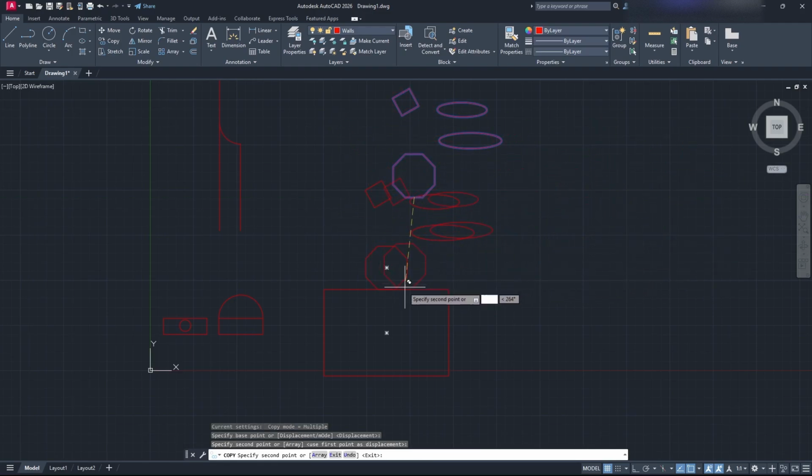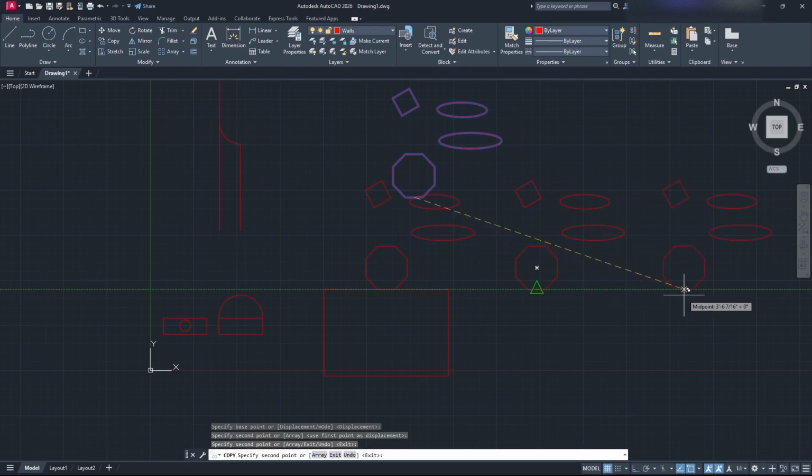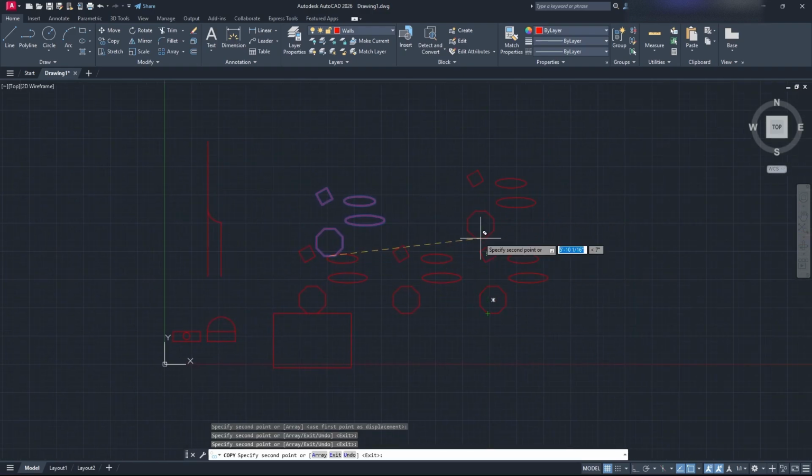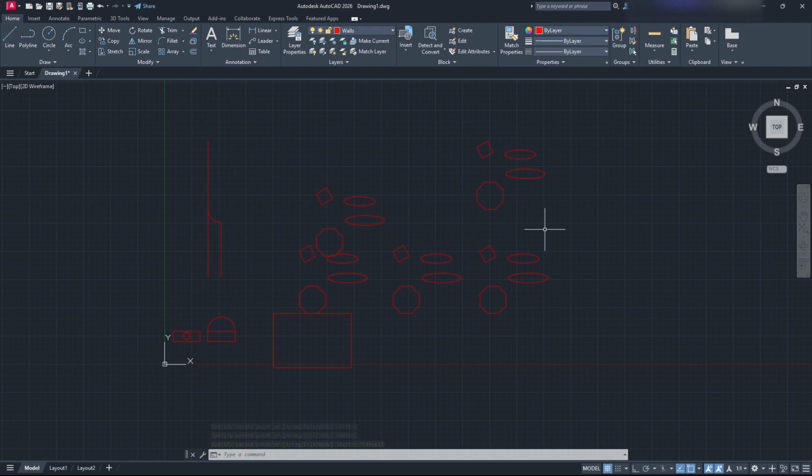And the thing is, when you use the copy tool, because there's two ways you can copy. You can copy the way we're doing now, or you can do just the standard copy, where if you've used Windows for any period of time, you know, if you hold Control and press C, that's going to copy things. That also works. And if you hold Control and you press V, that's also going to copy things. The difference with this is it's going to keep copying until I cancel the command. So you can see here, it's going to just keep copying until I cancel the command. So I press Escape. So for everything when you're doing this, you want to press Escape. And that's for drawing as well. Press Escape when you want to cancel a command. So keep that in mind.